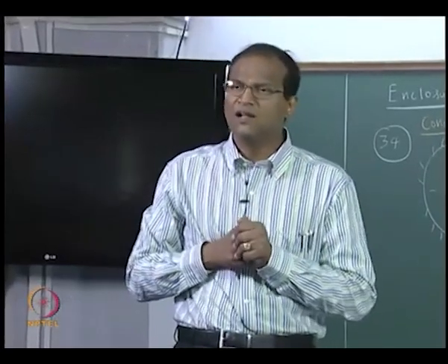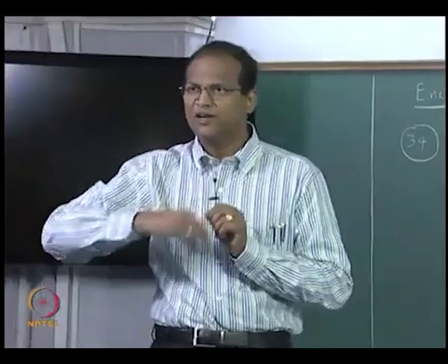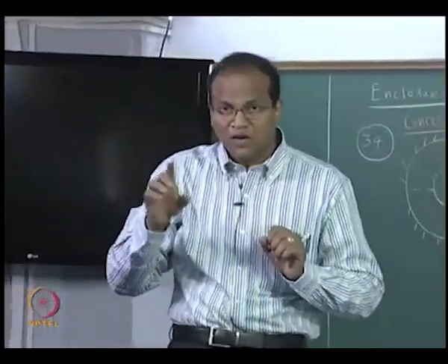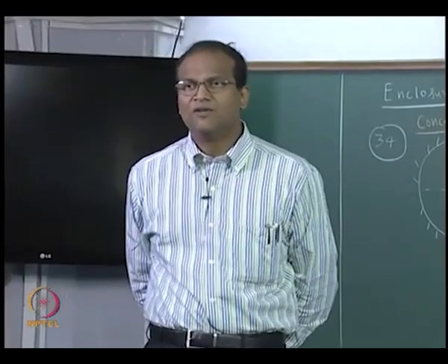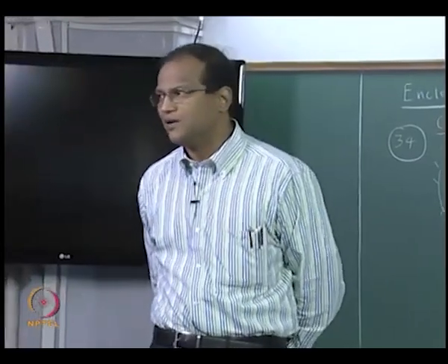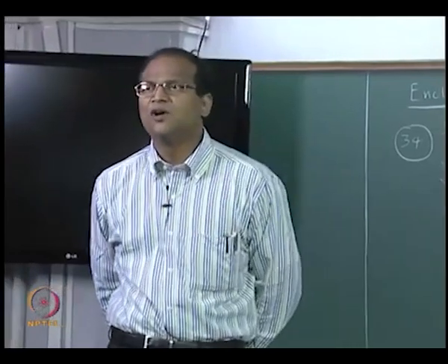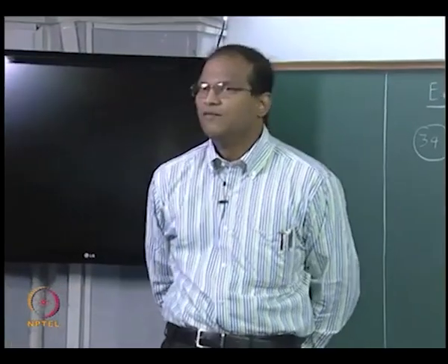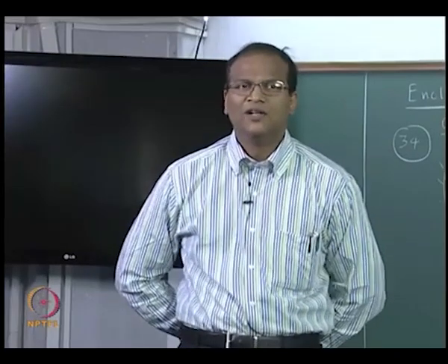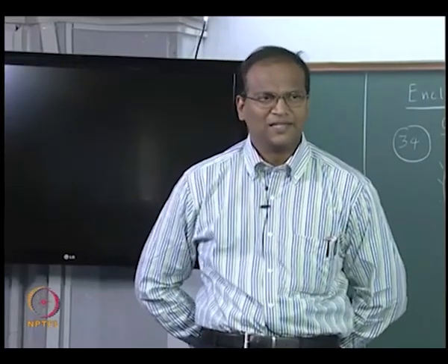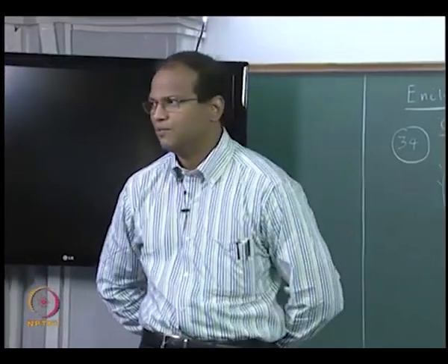Now you can see that it will take 15 or 20 minutes for us to get through this algebra, is very, very painful. Already we saw the parallel plate formula itself, I did so many things, right, epsilon 1 sigma T to the power of 4 minus epsilon, I divided by epsilon 1 epsilon 2 throughout and all that. Apart from all this epsilon 1 epsilon 2 confusion, we will have the A1 by A2 confusion here, okay. So there is ample scope for you to make mistakes, take a minus as plus and put A2 by A1 instead of A1 by A2 and so on.